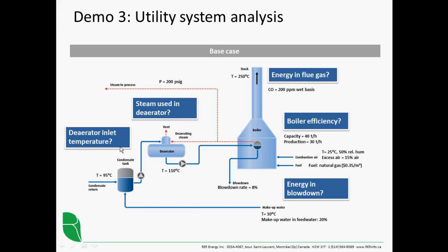And then I might also want to know a little bit about opportunities for heat recovery. So, for instance, how much energy is available in the flue gas for heat recovery? How much energy is available in the blowdown? So that's the first part of this.